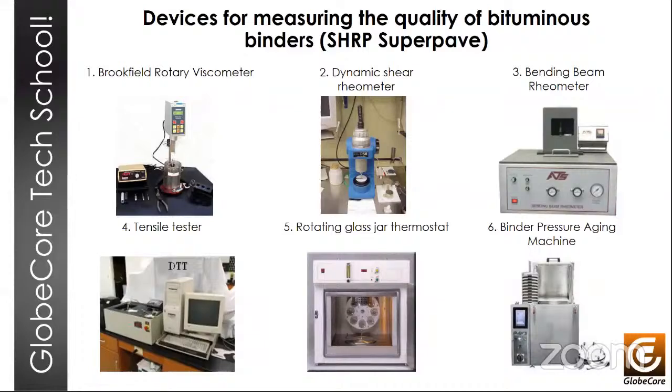It should be noted, however, that the existence of the SHRP Superpave system does not mean a complete rejection of the previous bitumen quality indicators. In laboratory practice in the United States, the depth of needle penetration to identify the AC20 grade of bitumen, flash point, solubility in organic solvents, true density, and softening point are also used. These indicators in the USA are part of the so-called SHRP Plus package of requirements.